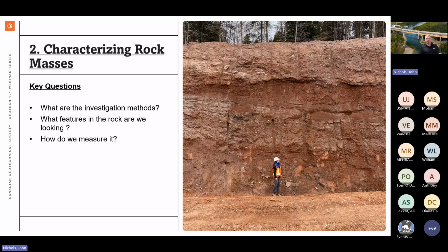You have to dive into the mapping, the structure, historical reports, and you need to create your geological model, which should include rock type, boundary conditions, if there are faults, which is often overlooked, even how the existing units fit together, if there's intrusion, any weathering or alteration, all sorts of events. And again, setting out a good plan, knowing the potential complexities and difficulties at the site, is an important skill for a rock engineer.